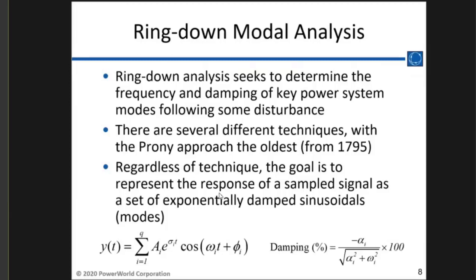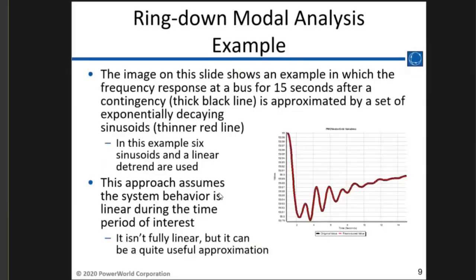So now we're going to go on and say how that wasn't very good. We don't use Prony. Since then there have been a lot of techniques developed, and they're surprisingly good techniques. They weren't necessarily developed in the power community, but they were something that we can utilize. So regardless of technique, the goal is to represent the response of a sampled signal as a set of exponentially damped sinusoidals, or what we would call the modes in the system.